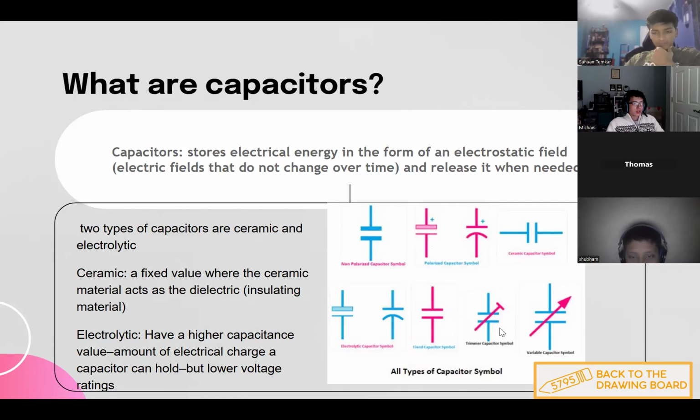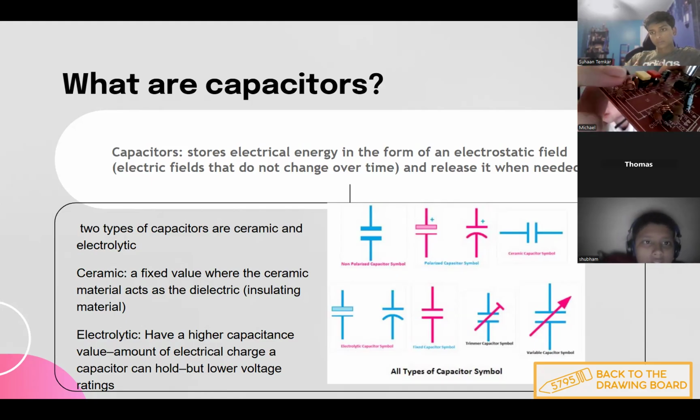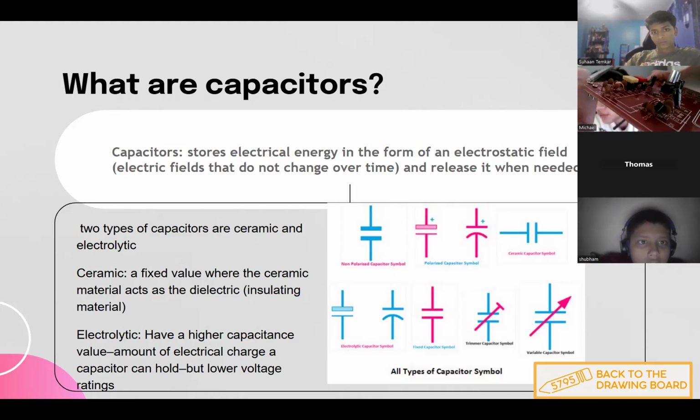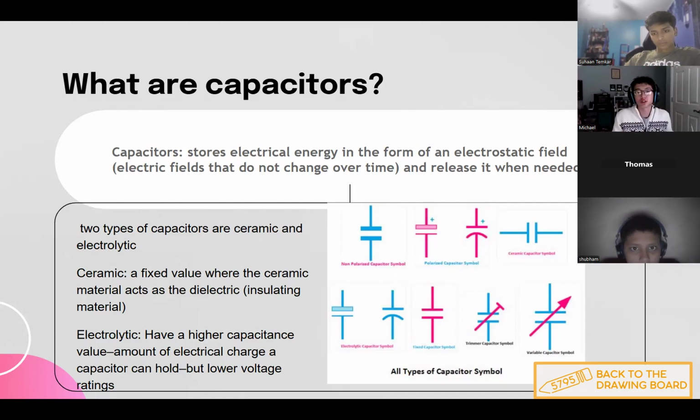Yeah. There's just a lot of different types of capacitors out there. The general type of capacitor, important ones are the non-polarized capacitors. So those would be your ceramic capacitors, and I think I have one right up here. If you look in this top right corner, it's kind of hard to see, but all those little caps that look like circles, those are ceramic capacitors, and they don't have a polarity. That means you can plug them in backwards, just like resistors. You can mix up plus and minus; they work the same. And that would be the symbol for